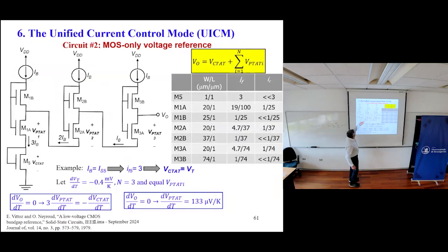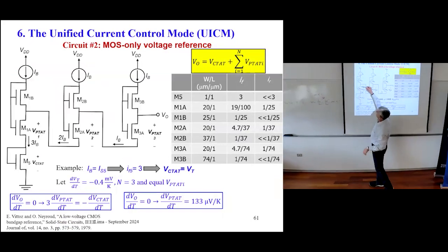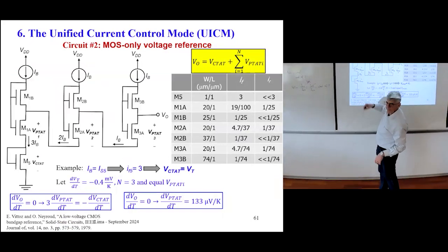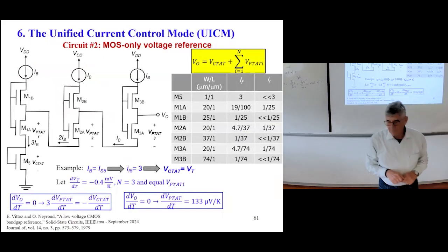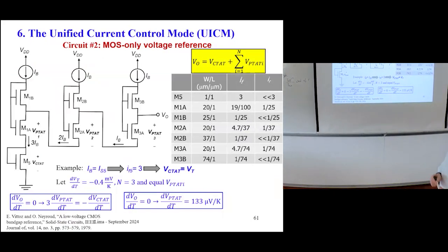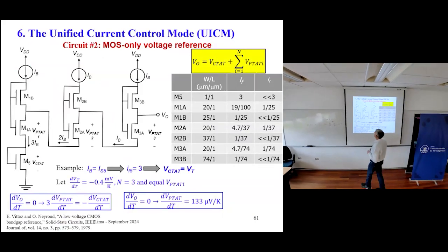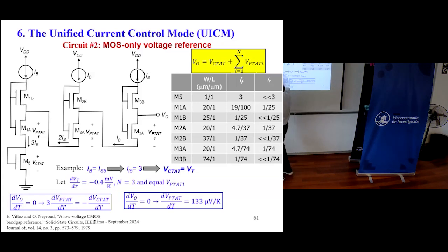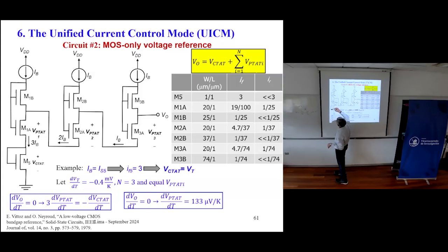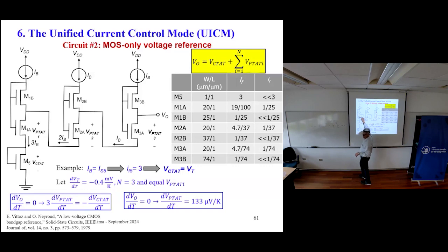You have a lot of self-cascade MOSFETs here, right? One different self-cascade with three transistors in the connection. But the self-cascade here is just this one, because this one doesn't share the gate voltage with this one.